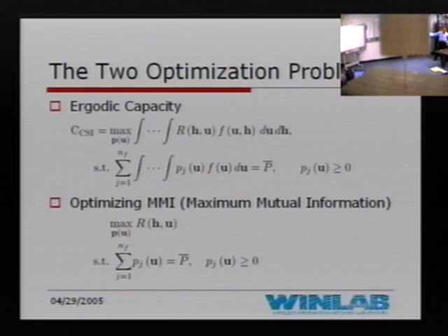It's true that this might also lead to problems: if I have a very bad channel, I transmit something and get very low rates, and I have to transmit it again. But that's not really what I'm addressing here. I'm saying that here, for each given channel realization, I'm transmitting something. To put it in simple terms, in the second case his total transmit power is constant. In the first case, his total transmit power varies, and he adapts it in time. That's the biggest difference. So in case one, he has more freedom to allocate his power.